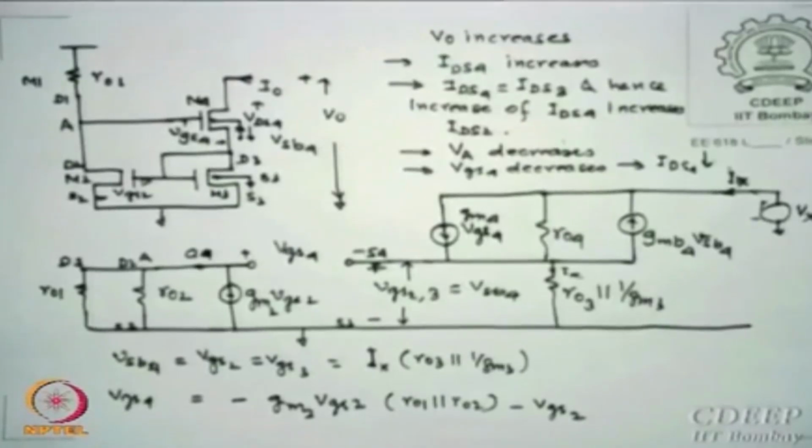So I am not saying this is the method, but this is a much simpler method of doing things. I am saying this from my experience, but you can do much better, you can simplify circuits. What is the other method? For each stage find the equivalent Thevenin source and Thevenin resistor, replace there, and keep doing that. That also is an equally good method. But in doing that, essentially you are partly doing the same thing which I am doing all together, is that correct?